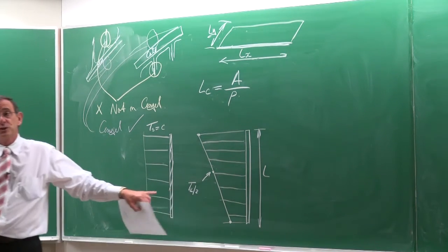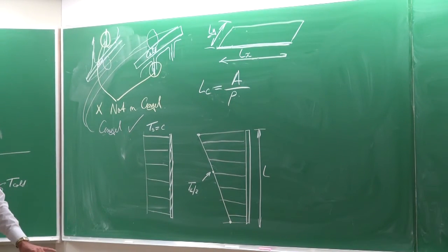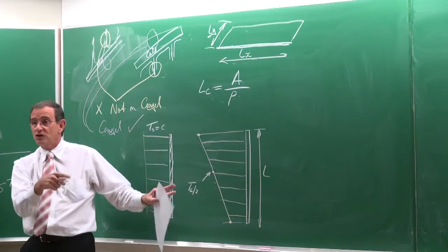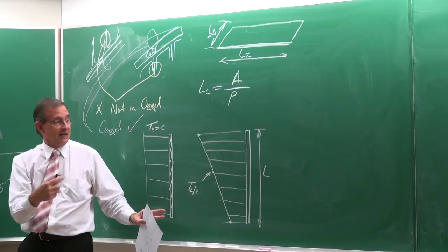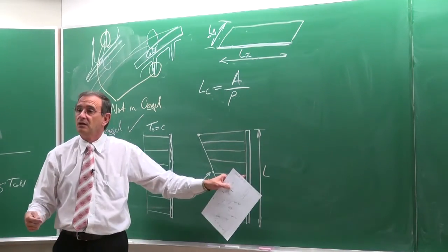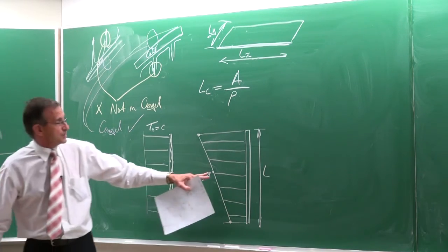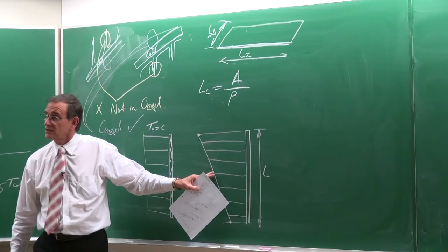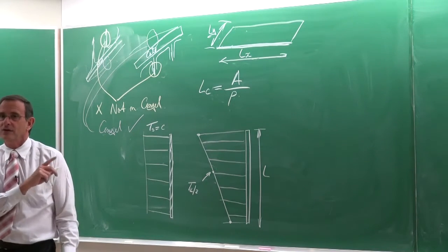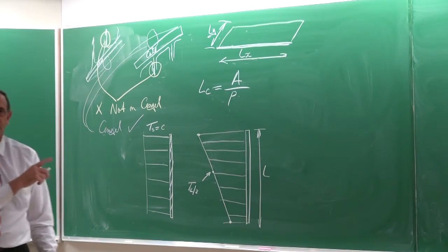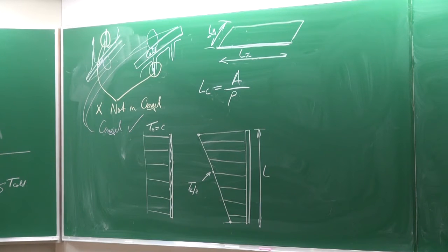Now normally when you start a problem like this, you wouldn't have this temperature, which means that you will have to guess a temperature, work the problem through, get the temperatures, and then iterate. So this problem is specifically much more sensitive to your starting condition and this specific temperature here. Okay, so please take note. This is one where I can catch you out in the exam. Okay, for the constant heat flux case, you have to be very careful.